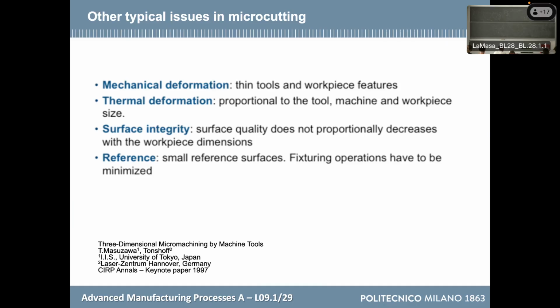If you look at our site, Polymill is the name of my laboratory. There is a component that we made for the Dynamis team, which is called the A-arm. It is a joint where they attach the links of the wheels. That component is a complex one, so you can have an idea: what we did was take a block of aluminum, machine it everywhere, and leave only a thin wall. With the last pass in hot milling, we reduced that thickness to a value where you can take it away by hand. Obviously, you will see something there, but if you selected the right position for that wall, everything else has been machined without removing the part. So you can replicate the precision of your machine. If you have a good machine, you stay at the micron level.